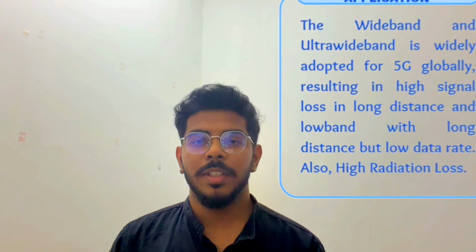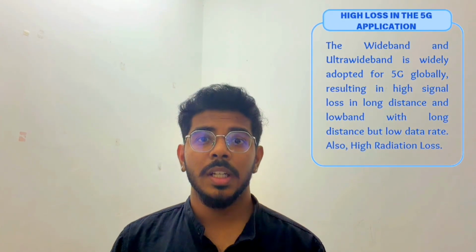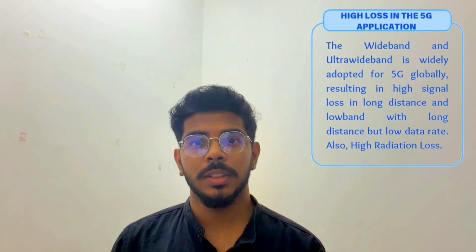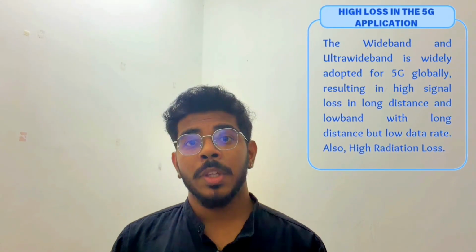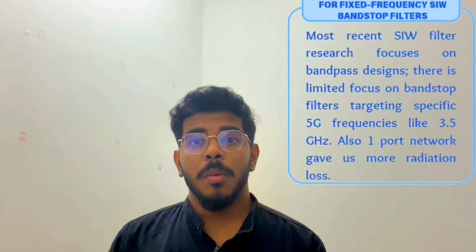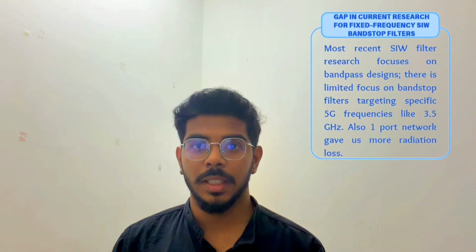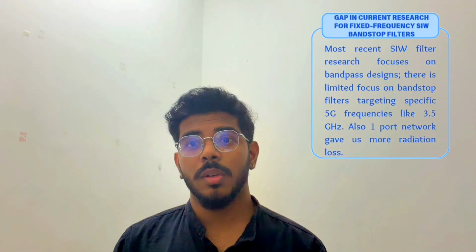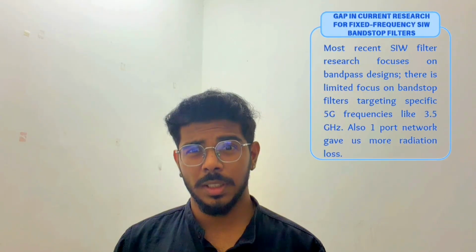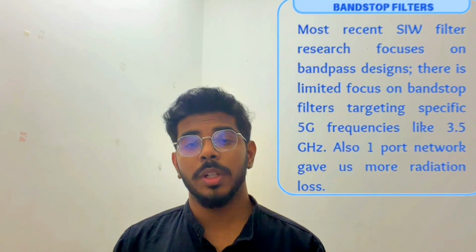Firstly, high loss in 5G applications. Wideband and ultra-wideband are widely adopted for 5G globally, resulting in high signal loss over long distance and also low bandwidth over long distance, which gives us a low data rate. Also, it affects the high radiation loss. Secondly, most recent SIW filter research focuses on bandpass designs, and there is limited focus on bandstop filters, especially targeting specific frequencies for 5G like 3.5 GHz. Also, a one-port network gives us more radiation loss.